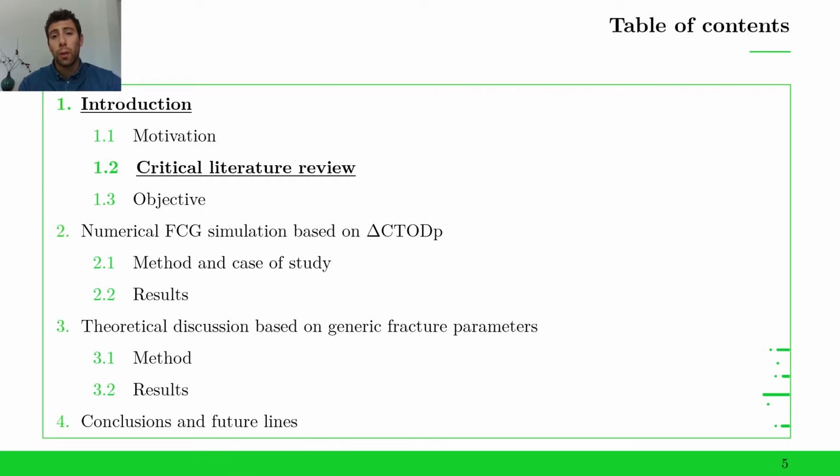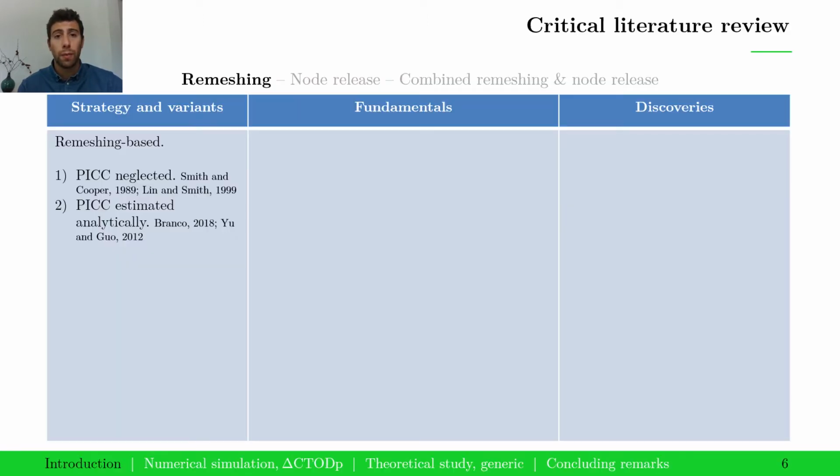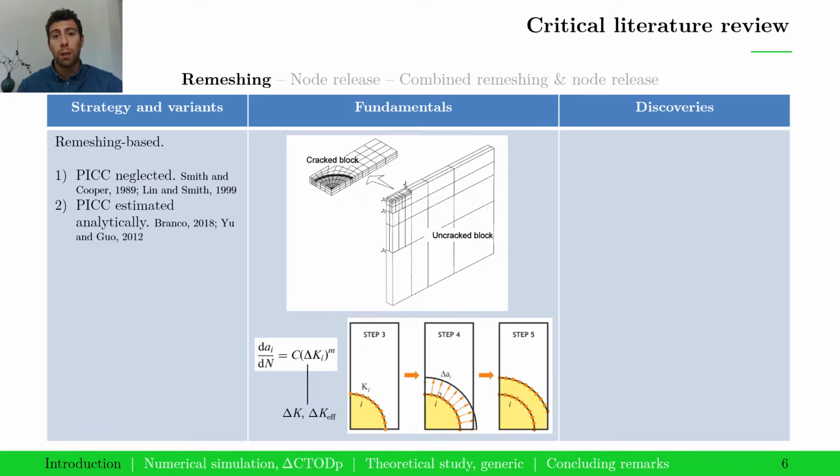Reviewing the literature, we see that there are different strategies. Some of these strategies are based on remeshing, and they either neglect plasticity-induced crack closure or they estimate PICC by closed-form expressions. These strategies are based on a 3-dimensional linear elastic finite element model of the cracked body for SIF calculation, and the crack is grown according to a multiple degree of freedom scheme following Paris-like laws.